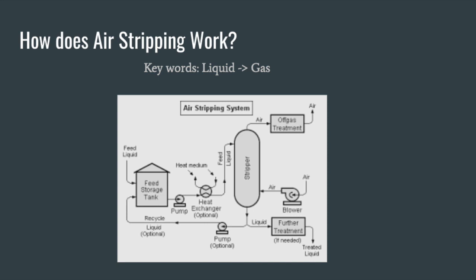very easily and quickly. The air passing through the contaminated water helps evaporate VOCs faster. After treating the water, the air and chemical vapors are collected, and then the vapors are either removed or vented outside if VOC levels are low enough. Air stripping is commonly used to treat groundwater as part of the pump and treat cleanup method.